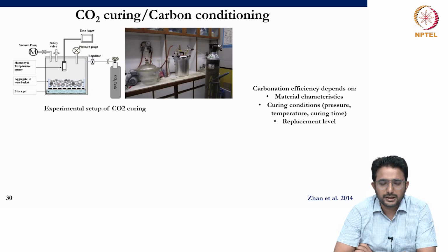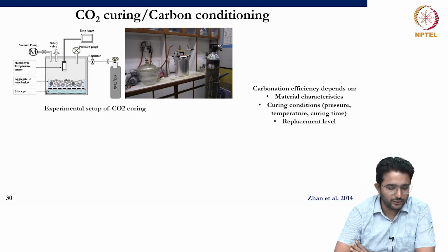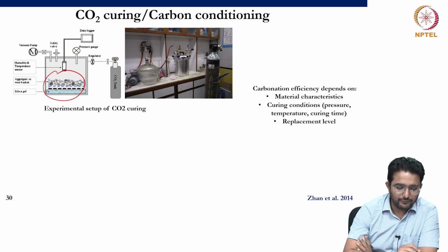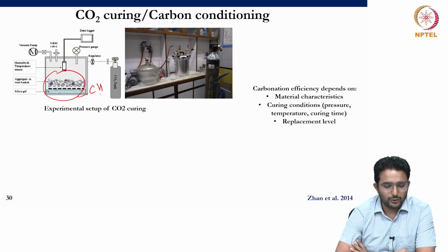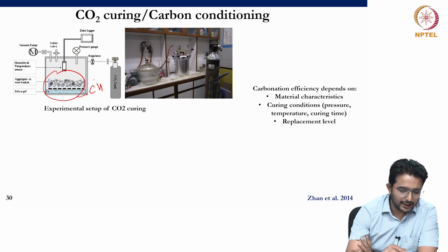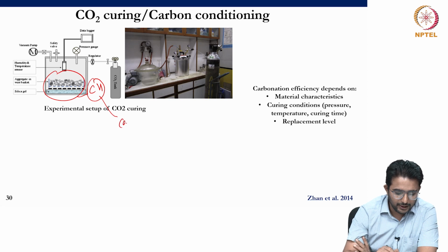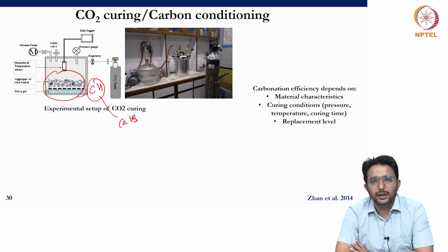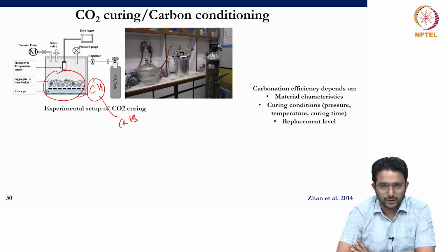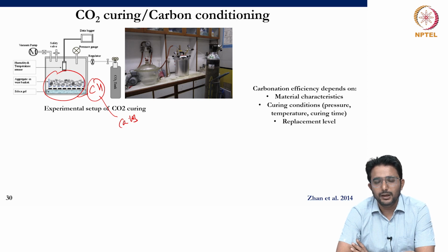However, the other self-healing technique is through carbonation. So what we can do, we can use the aggregates, and we know in the adhered mortar, calcium hydroxide will be there. So the carbon dioxide can be fed into the system under pressure, and then it can react with calcium hydroxide and form calcium carbonate, leading to the improvement in the properties of the adhered mortar. But mostly these techniques might not be adopted into the field, right?